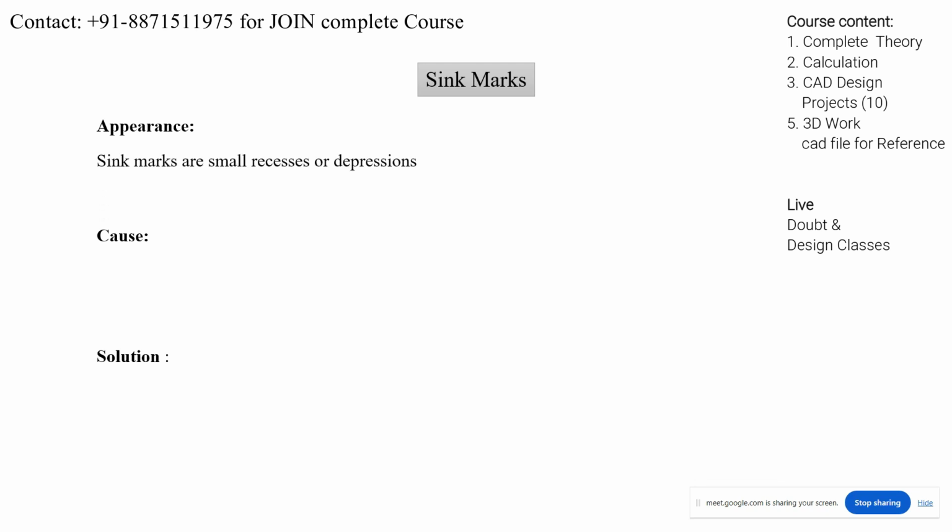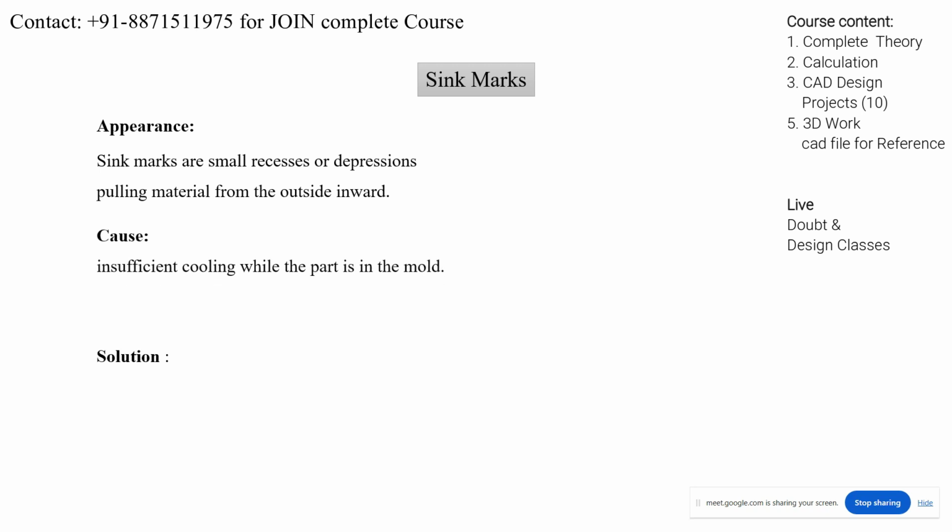Okay, sink marks are nothing but small recesses or depressions on the surface, right? So what is the reason for that? I'm showing it appearing right now. See, pulling material from the outside inward, right? See, what is the cause? Insufficient cooling while the part is in the mold. Insufficient cooling, right? Okay. Acha, what is the reason for that?